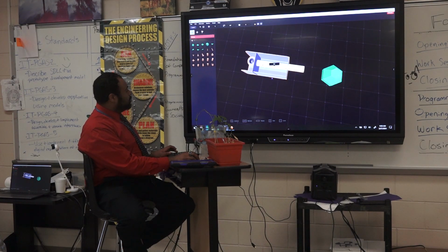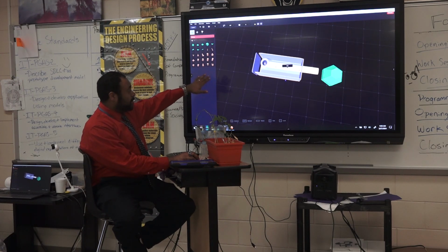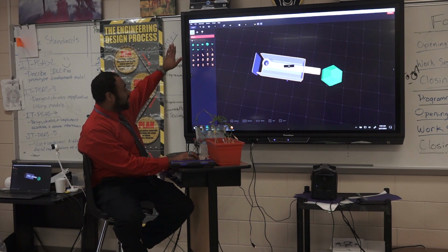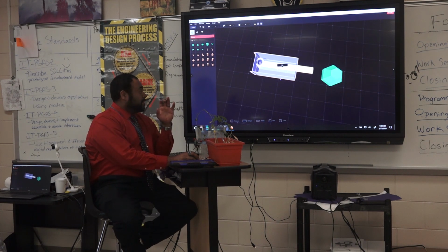So now when I move this, and of course I didn't select the wall, I made a mistake. But when I do that, holding shift and selecting everything that you want to move, you go up to edit and then select group. Or the shortcut key is just G. That is pretty neat. And then like that, I can just move this wherever I want to.